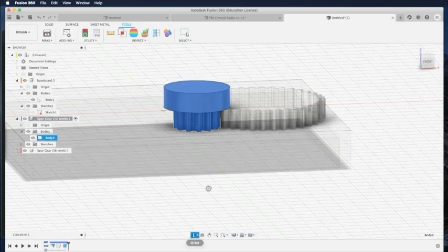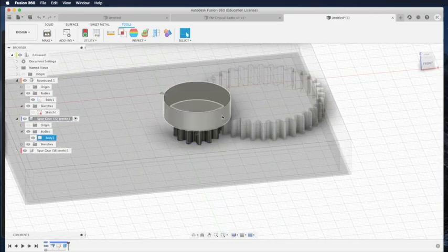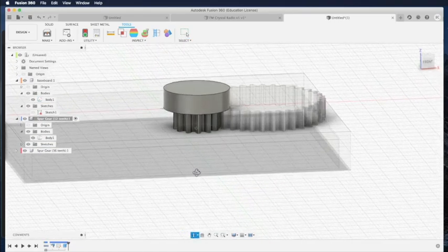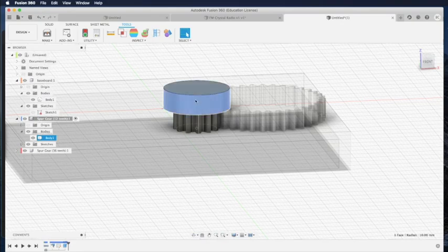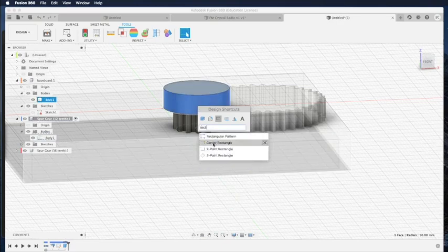So next we need to do some cosmetic work on the knob. Because the knob will be too smooth, it's hard to be held by a thumb. So we need to print some patterns on the knob, like the regular knob you can buy on the street. So how do we do that? To do that, we'll highlight the edge of this cylinder, this face here, and then we press the S key. This again selects the rectangle, center rectangle.